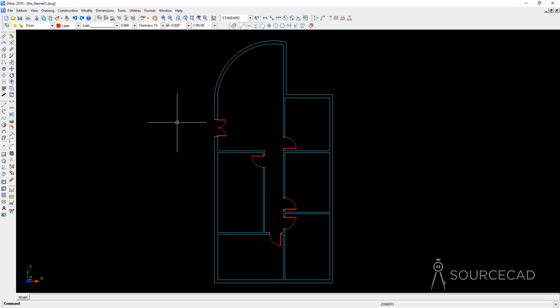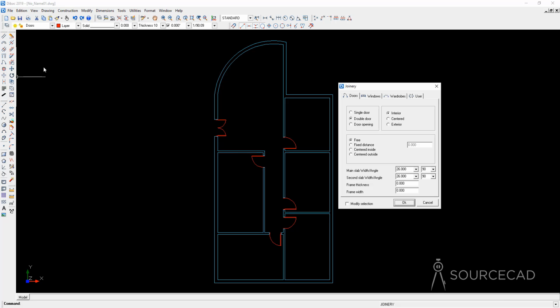So we have the doors. In a similar way, we can add the windows. So I'll go to joinery and I'll go to window here, and we also have the window sill, sill nosing, and large window. In this case, I'll add the sill nosing window, and number of sashes to the length is 48 inches, which is obviously 4 feet wide.